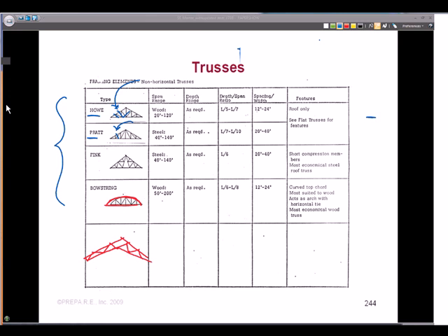When it's a tapered top chord, this is the direction of the diagonals. So the diagonals are always in compression, the verticals are in tension, and it's just the opposite for the Pratt truss. Okay, so these are various trusses to get to know, if you don't know those, just to be able to identify various systems and their advantages and disadvantages.